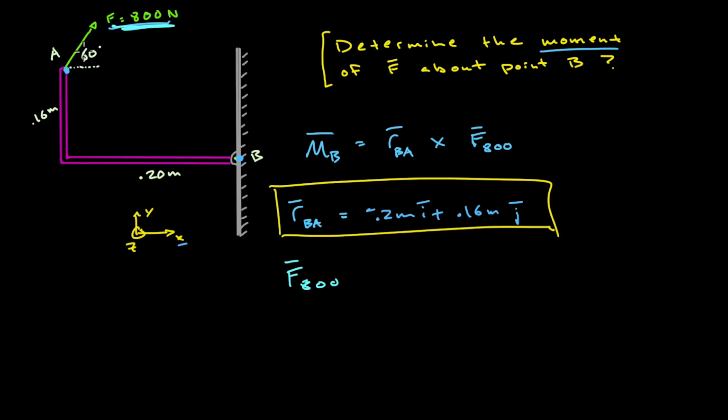So looking at this green force right here, that's a vector, and it's got some component in the x direction and some component in the y direction. Now, this is a 2-dimensional problem, so there's really no need to involve the lambda approach where we've got the unit vector that points us in the right direction. Typically, we'll use the unit vector approach for when forces are in 3 dimensions, and it's less obvious how we can use basic trigonometry to decompose the force.